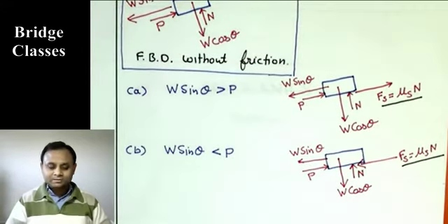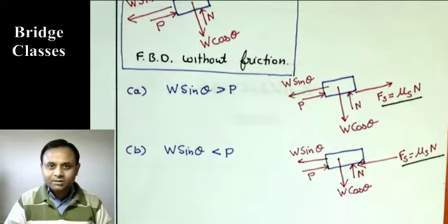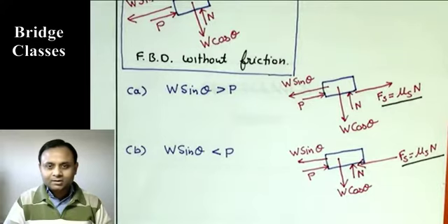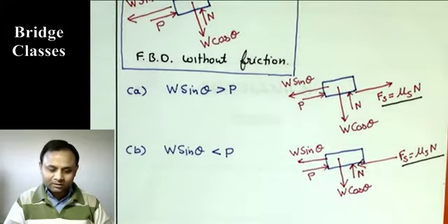So we discussed so far the kinetic friction, which is mu k N, and it acts opposite to the actual motion of the body. So that is simple. Then there is static friction under the situation of impending motion. The frictional force is going to be mu s N, but its direction we will have to figure out the way I explained here.